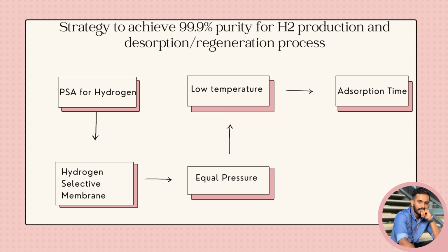For the equal pressure, an equal amount of pressure is applied to the directed bed or flow of the stream, which can be seen in the designated column, where the amount of pressure is equal to the previous column. This increase in pressure will cause the purification of hydrogen to increase, but it was determined later that the recovery of the hydrogen is very low.